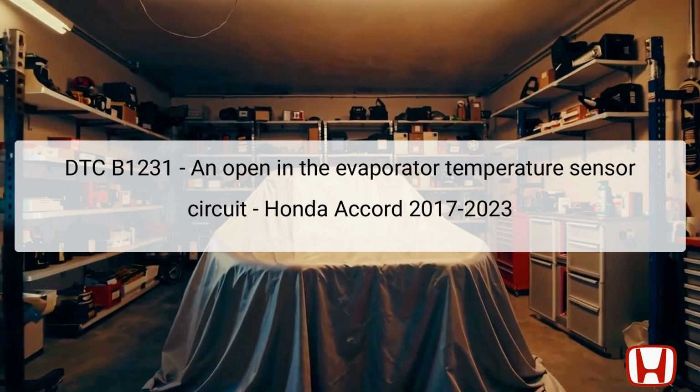When the evaporator temperature sensor circuit is compromised, the vehicle's climate control unit cannot operate correctly, potentially leading to inefficiencies in cooling. The sensor is generally located near the evaporator itself within the HVAC unit. This diagnostic trouble code, DTC, is important for maintaining driver comfort and the overall functionality of the vehicle's air conditioning system.